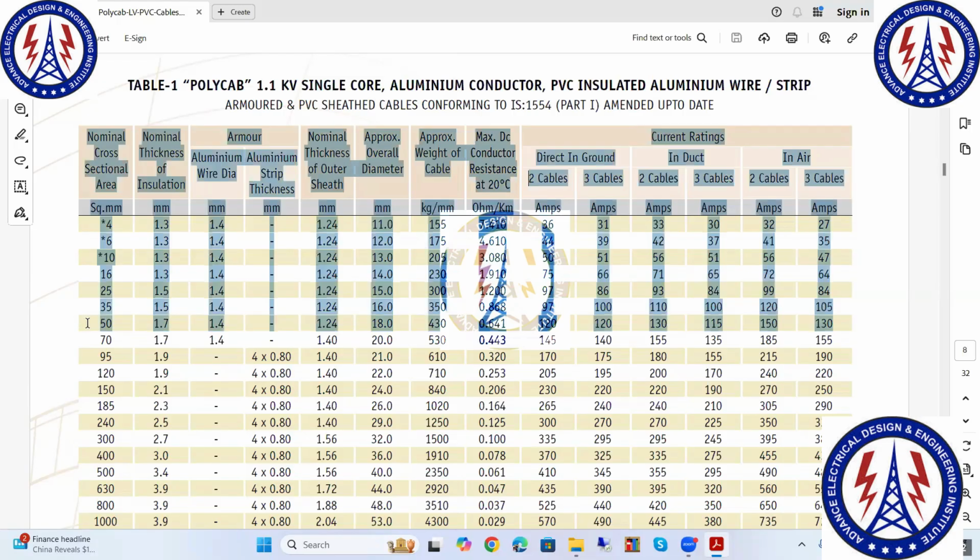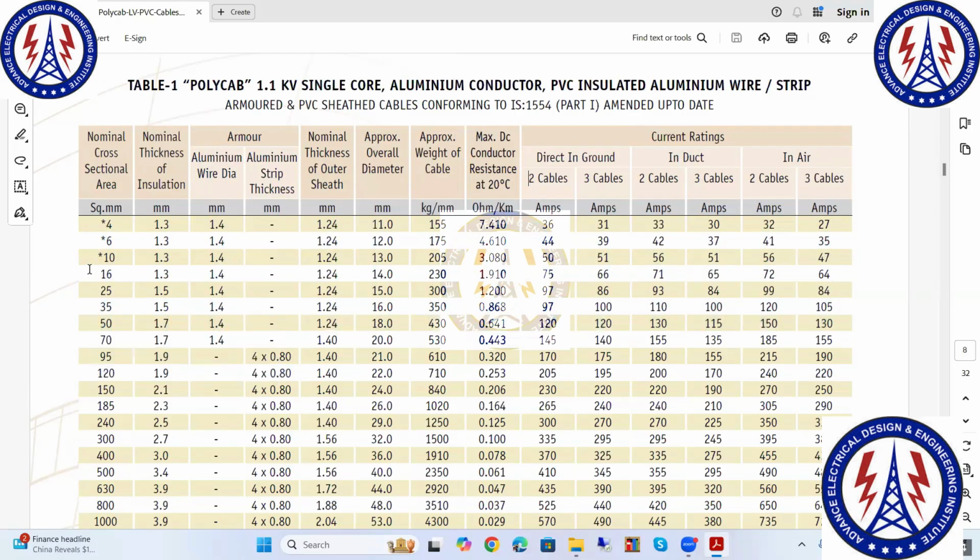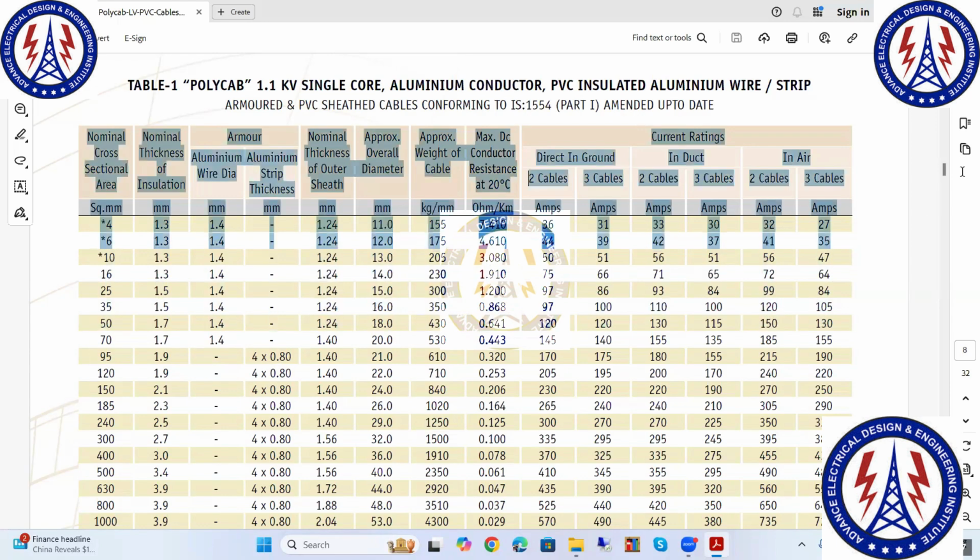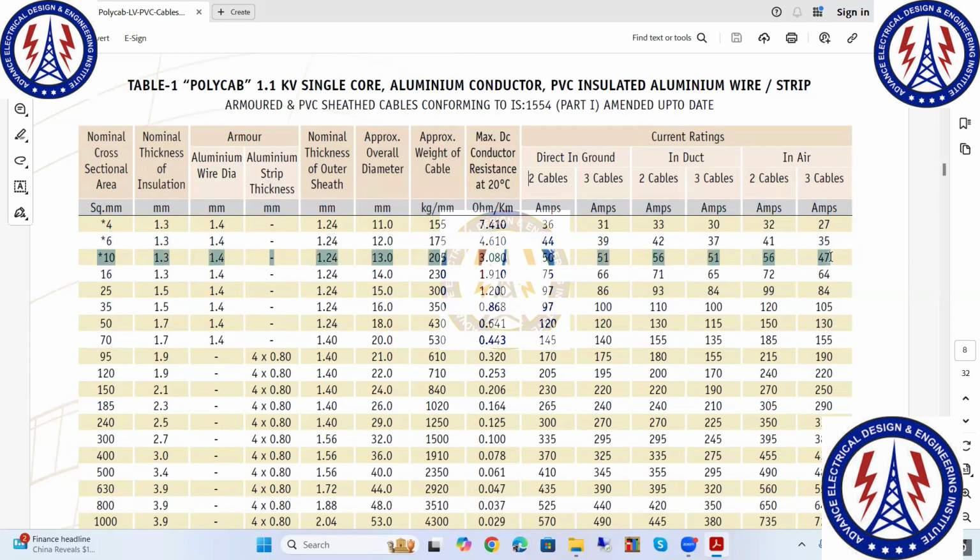The main point why I asked is, suppose the length of cable laid is not considered for the current. If it is 10 meters, the current given is okay. If it is 200 or 300 meters, then the current will vary, right? No, no. Only the voltage drop will change. Current will not change. Voltage drop will vary, correct. That we will calculate as part of the cable sizing based on the load. Just after this introduction, I will move toward the sizing. This is the input data which we're getting from the vendor.